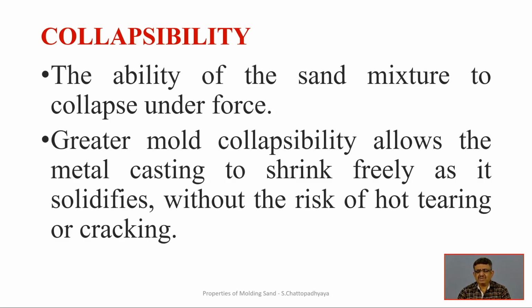So, though in some cases conventional methodology will be used, it is better to use appropriate collapsibility of the moulding sand, and then only can we quickly get the ultimate product. So, these kinds of features are also required, but sometimes collapsibility and strength contradict each other in terms of implementation.